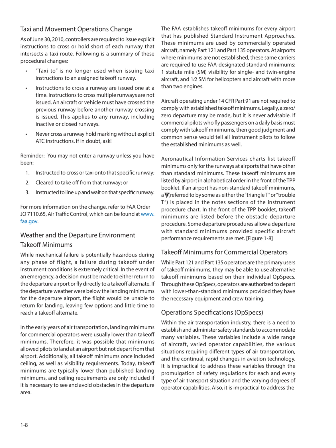For more information on the change, refer to FAA Order JO 7110.65, Air Traffic Control, which can be found at www.faa.gov. Weather and the departure environment, takeoff minimums. While mechanical failure is potentially hazardous during any phase of flight, a failure during takeoff under instrument conditions is extremely critical.